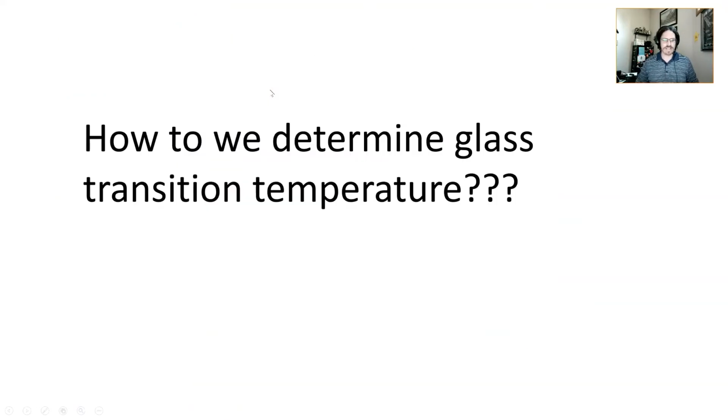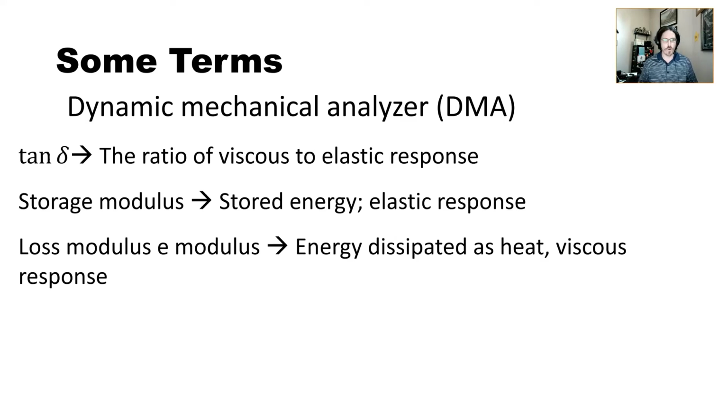So how do we determine the glass transition temperature? Well, you've seen the video: Dynamic Mechanical Analyzer, DMA, and also Dynamic Mechanical Analysis, DMA. Start thinking about some terms here. So tan delta, and this is also used in dielectric materials. We're using it a little bit differently, but it's still the same thing because it's still a frequency response. That's why we see similar terminologies to what we see for characterizing dielectric materials.